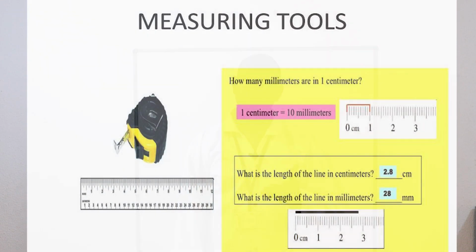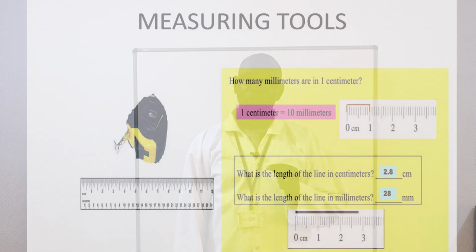On the other hand, the compass is used to transfer measurements from a measuring tool, such as a measuring tape or steel rule. For example, you can open the compass to 10 mm and transfer the 10 mm measurement to the workpiece that you intend to cut.